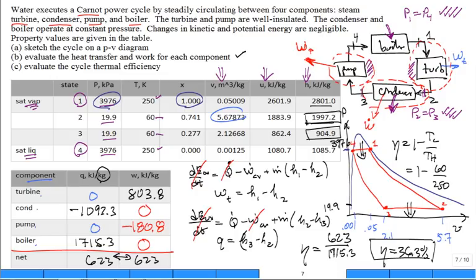And it's degrees C. So I fix it by adding 273 and adding 273. The temperatures have to be in Kelvin. This temperature is degrees C. I'm sorry, I didn't correct that fix. And now you'll get 36.3% thermal efficiency. It'll be in agreement, okay?